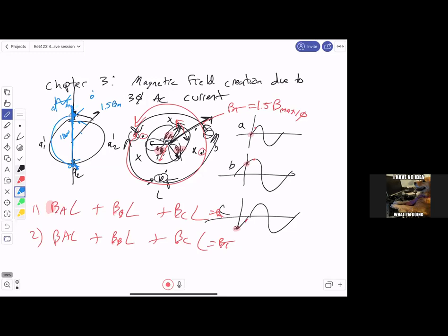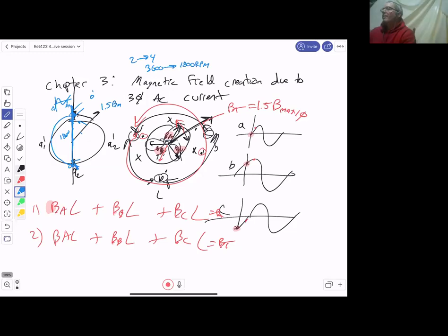So what I've done is by adding a number of pole pairs, or a number of poles, I've gone from a 2 to a 4 pole machine to get 360 electrical degrees. I only have to operate at half speed. So that means that instead of 3,600 RPM, I can run at 1,800 RPM. So that's how, in the real world, we actually get motors to increase or decrease speed in sort of a discrete step. We enter it that way and we work it that way.